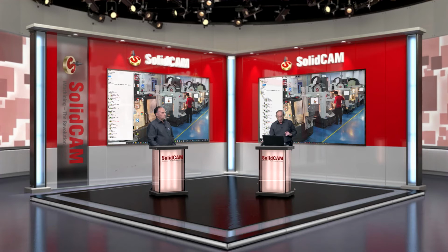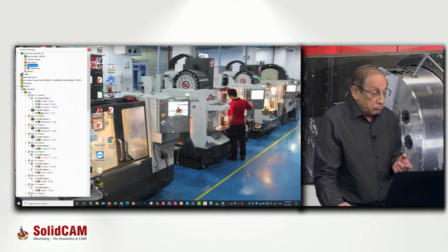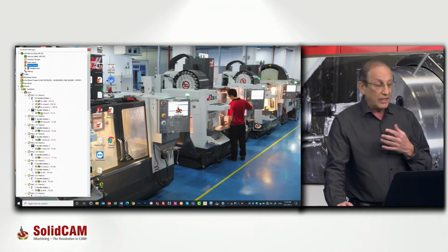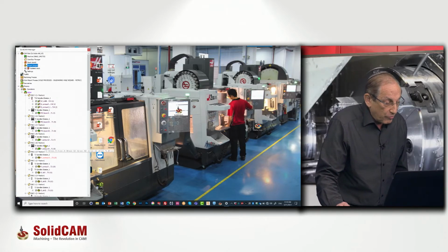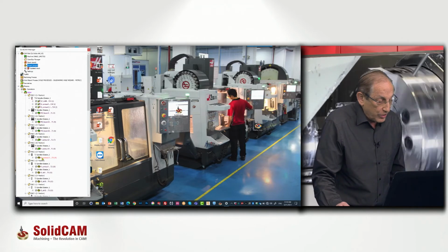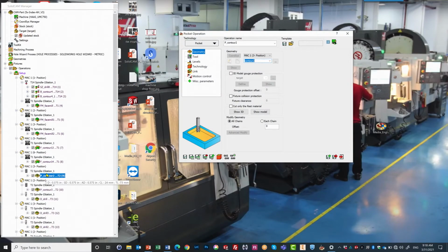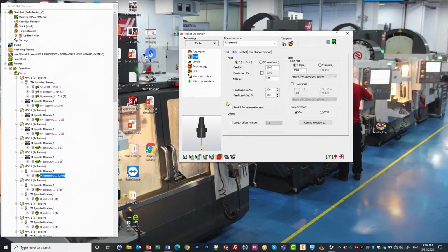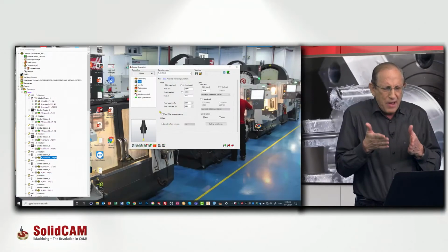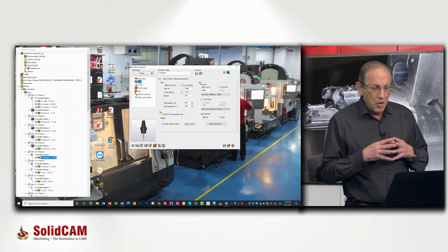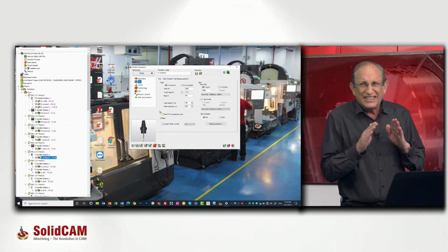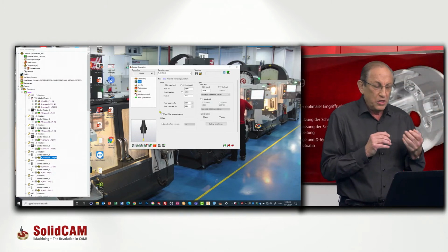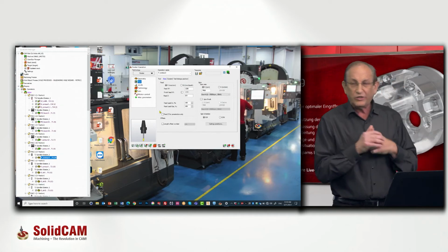Okay? Now, I have all the operations over here, and I can do whatever I want. For example, let's say I'm going to go into one of my operations, a pocket operation that I have over here. I happen to know that if I look at the tool and I look at the data, the programmer made this with the knowledge that he has. But the knowledge that I have tells me that this particular machine on the shop floor is a little shaky. It's not exactly well-tuned. In other words, it's a little old. The feed rates and the spin rates are not exactly right, so I can make those changes right here.